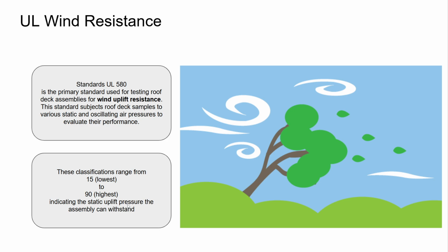And you don't have to know much about that, but when wind blows over a roof, there are some equations that tell you that because it's moving faster, it makes a suction. So it actually sucks the roof upwards, and you have to be able to resist that. So a 15 uplift is not very strong, and a 90 uplift is very, very strong. Your structural engineer will give you all that based on the codes for the area where you're building.